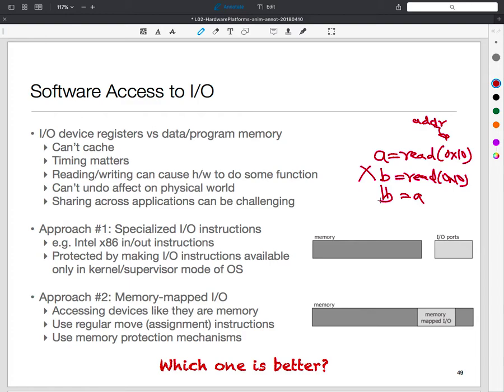So there's a keyword called volatile. If I say volatile int x in C or C++, then this volatile means that this variable is mapped to an address where when I say read x or do something to x, you better go and read it. So volatile is an additional part of our C and C++ language.